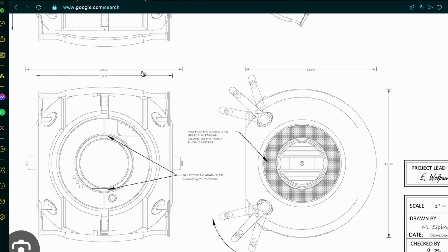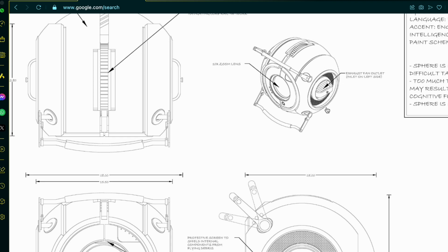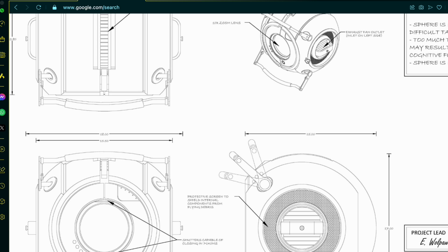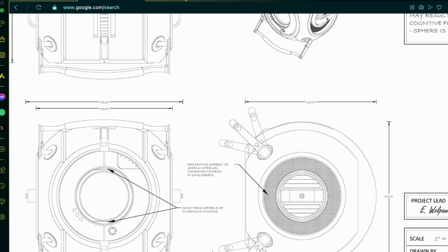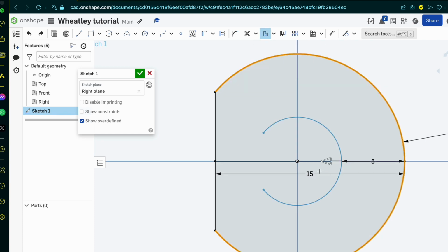Now we're told that we also have a thickness of 15 here and 18 here. So we can sort of ignore this section right here at the moment, because we're just focusing on this bit. Now, for simplicity, we're going to presume it's a perfect circle still. So I think what we should do is give this a shell thickness. There's two ways of doing this. The quickest way I find is to use the offset tool, snap this line, and then extrude this.